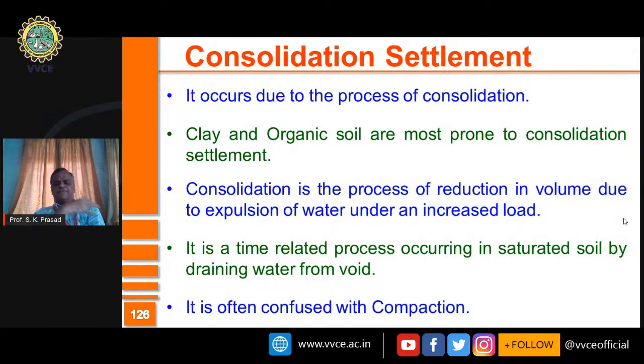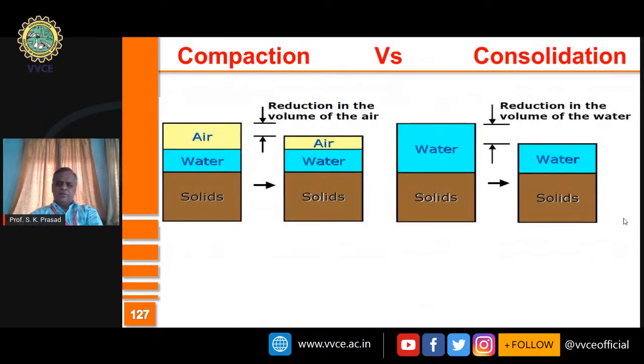So it takes a sufficient amount of time, and many a times people are likely to get confused between compaction and consolidation. I normally try to explain that compaction is a mechanical process. It is a fast process. The volume reduction is because of the expulsion of air, not water. It is seen in a partially saturated or dry soil. It is not seen in saturated soil.